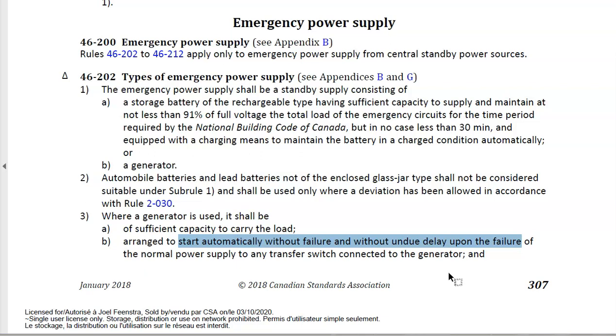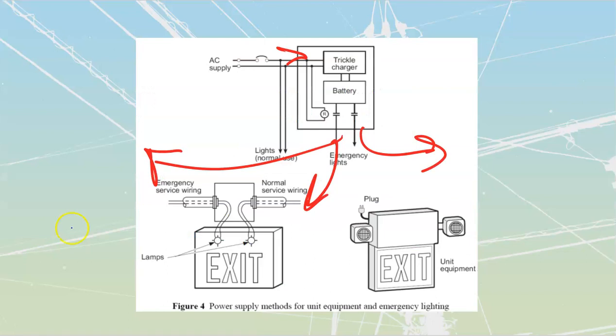If for whatever reason, let's say that I'm going off of a floors type of idea, we'll just draw that in over there. I'm going to have a central genset over here, and that genset might be going up to multiple different floors. And each of those different floors is going to have a transfer switch. Okay, I'm just going to draw in 2 transfer switches. Well, we'll draw in 3. So here's my generator. It's going to feed into this pole of all of these transfer switches. I'm drawing it as a one-line diagram here, but I think you're all sufficiently capable of understanding that.